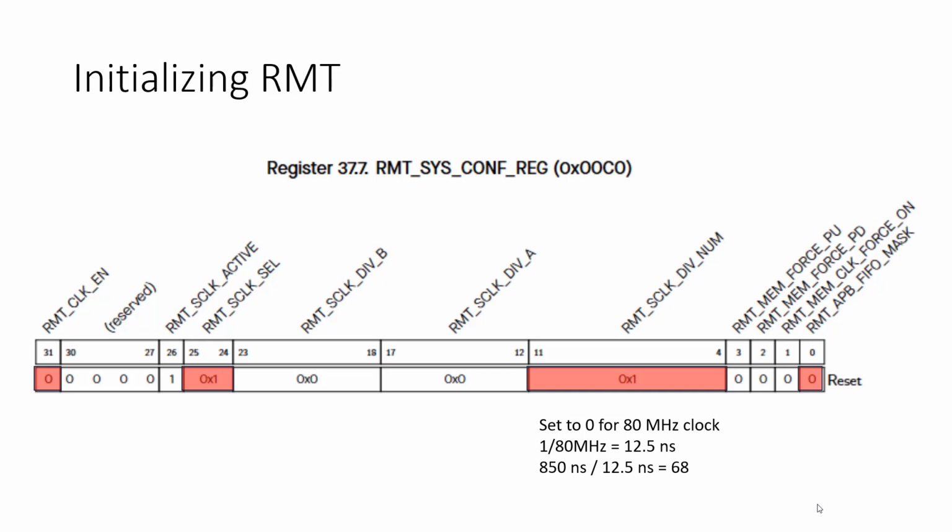So this is a separate clock enable. The clock we enabled before is like the master clock that clocks the RMT peripheral itself so we can access it. This is the clock that drives the bit stream that's coming out of the RMT peripheral. So it's two separate clocks. One of them is like the internal logic, and the other one is the actual pin drive. Yeah, okay. But yeah, so there are two.